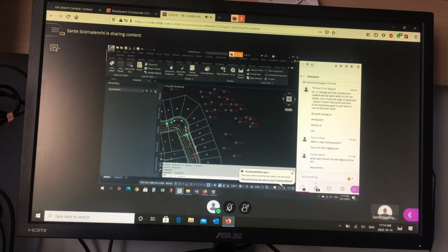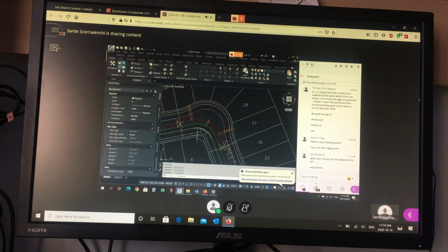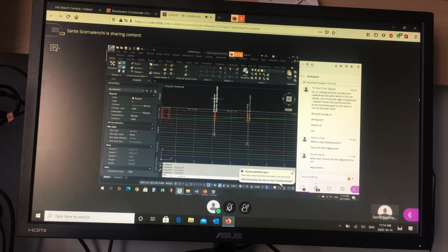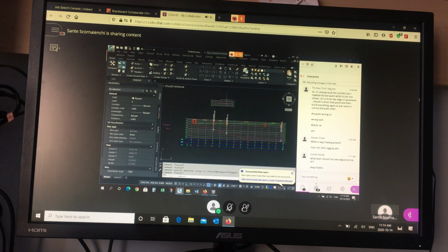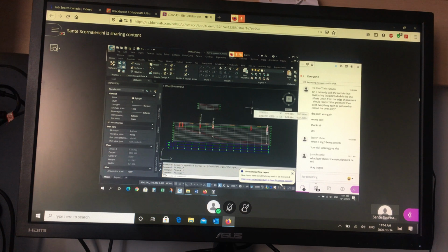alignment. Okay, and notice the length of the gutter is longer than the length of the center line. Right? The distance between these 2 points on the center line is shorter than the distance it takes to go all the way around the outside. And that's one of the things that we looked at when we decided what should this slope be so that the gutter line meets the minimum requirements. Okay? Any questions about that? Existing ground profile for the gutter.